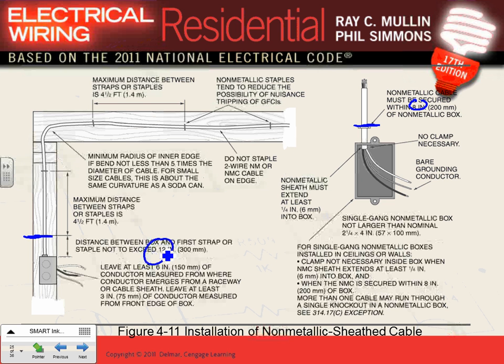You staple them at 4.5 feet intervals. That's it. Those are the rules you have to follow. Staple at 4.5 feet intervals, and at 8 inches if it's non-metallic, 12 inches if it's metallic from the box.